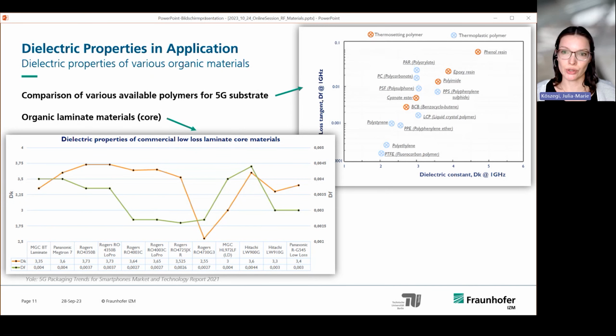This is really crucial, especially when you think about system design, where often you cannot adjust it linearly. If you have a bit more losses, you cannot just have a bit better amplifier or a bit extra of something. Sometimes you really have to have another module. So it's integer steps in your system components, and you cannot compensate that much for design. So the losses are becoming a really crucial part here.